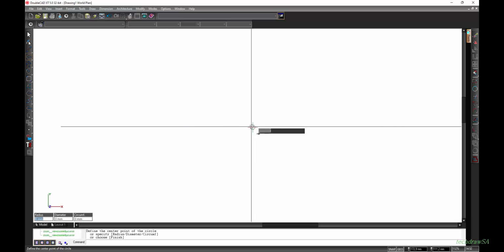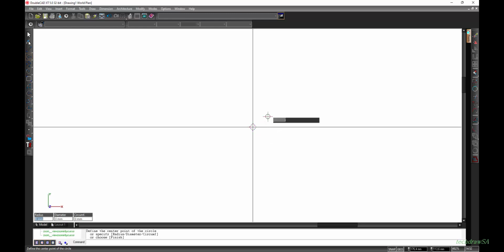So that's why I will zoom in and make sure that when I move my mouse around that little pink diamond snap aperture is definitely snapping to the point. So zooming in and out is crucial in any CAD software. You will learn that mistake very quickly: if your drawings are inaccurate or there are some issues that you find, normally it's because your snaps weren't proper and you didn't snap exactly on the lines that you wanted to.